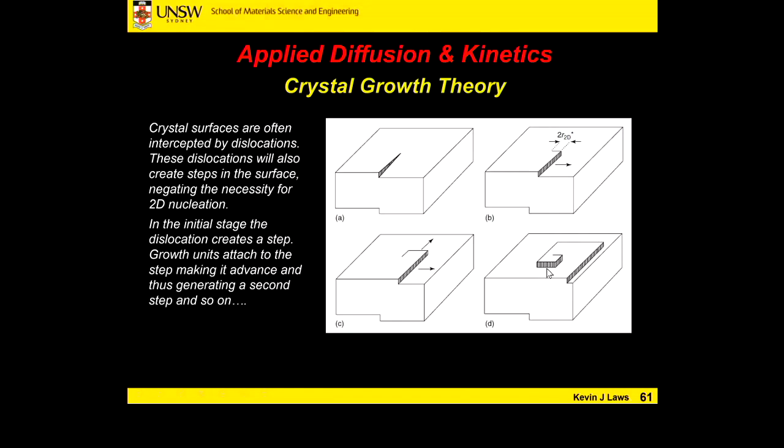But the main takeaway here is that defects also provide sites for accelerated growth. We kind of know this, and it also comes into play with recrystallization processes as well, that a material that has a deformation or a strain in it producing a flaw, the reaction rates occur faster. If we have a completely relaxed and annealed material, the growth rates are essentially going to be slower.